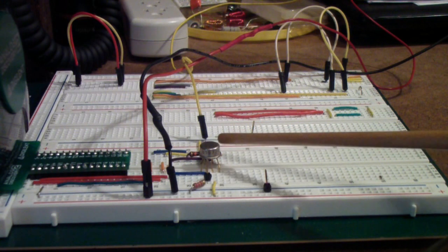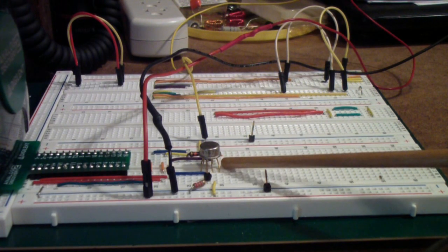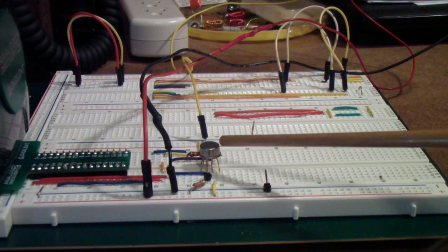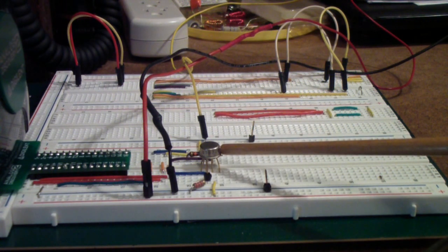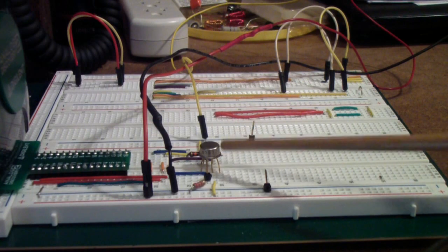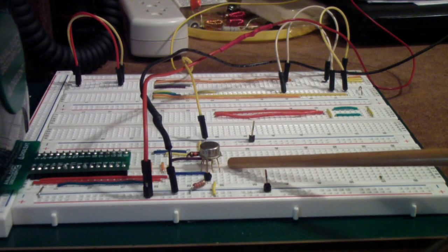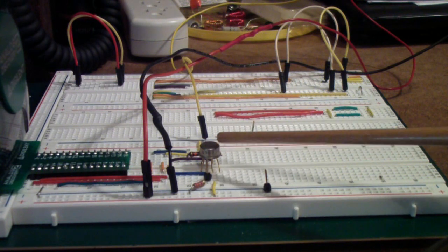And while you can improve the slew rate slightly by using higher supply voltages, when you reach the limit of the amplifier, of course, you can't push that any further. And there is no way you can do anything about this. In the old days, many amplifiers had an external compensation capacitor. And where you needed high slew rate, you could play with that compensation capacitor. Well, in the 741, you can't. It's inside.